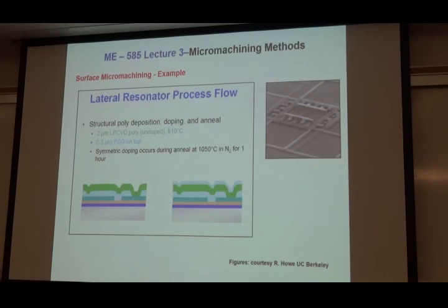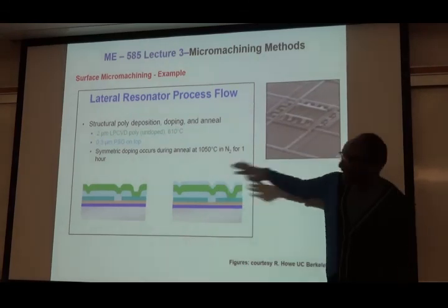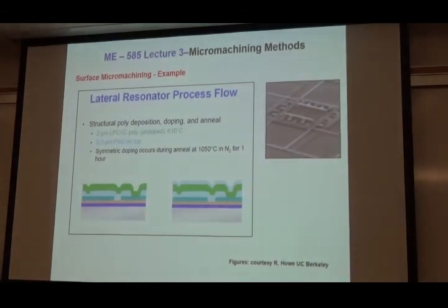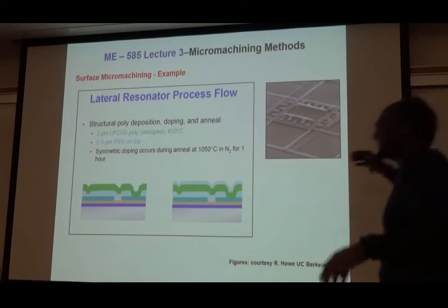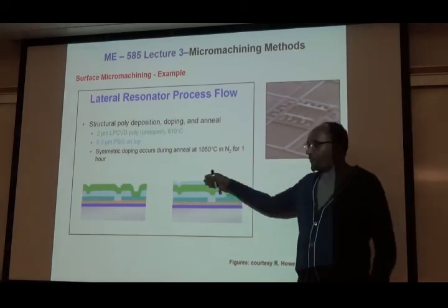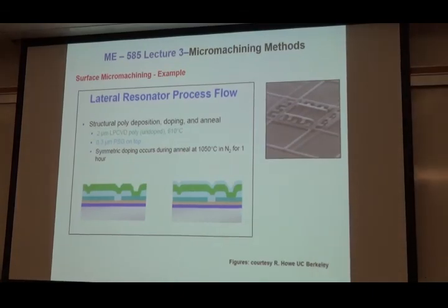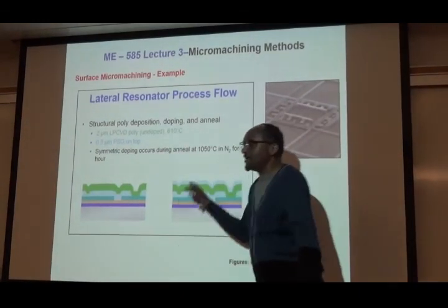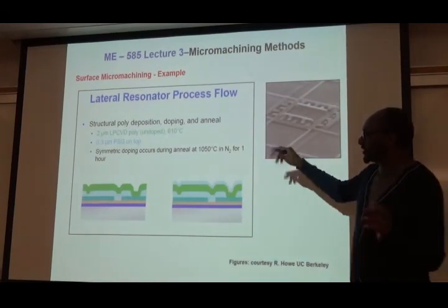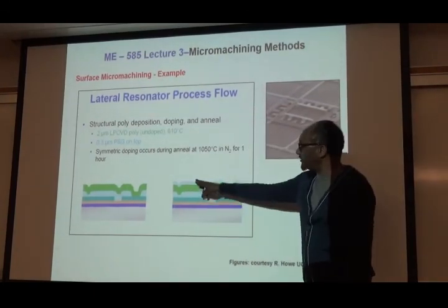But we're going to cover it again with the larger polymers process. But think of it this way. I'm going to use this glass, a thicker material, as a mask material. But to be a mask, of course, it has to mask not everything, but only selected areas. So if that's going to be the aim, then I have to have some of the areas at least darkened out, removed. And how am I going to remove them? Back to the old school, Shipley. So we're going to do a photolithography. So I have a mask, which is just called the PSG mask. You bring it over here, then you make openings.